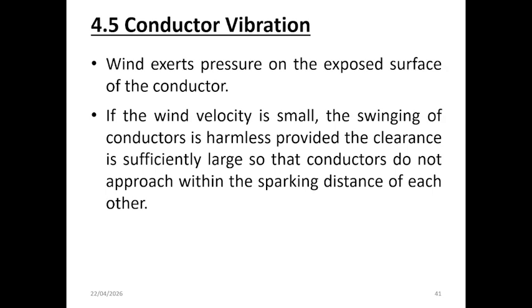However, the key safety requirement is that sufficient clearance must always be maintained so that even during oscillation, the conductors do not come close enough to each other, or to the earth or grounded structures, to reach the electrical sparking or flashover distance. If the wind velocity is high enough, it can connect conductors to each other. So this is very dangerous.